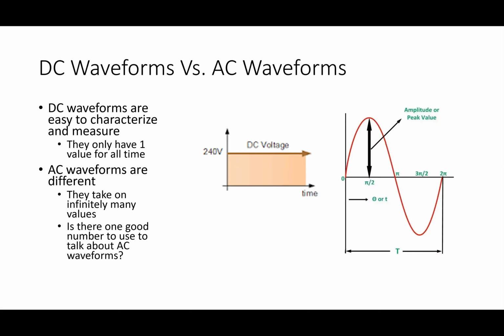And so we started out very naturally saying, well, if I'm referring to a particular voltage, you created a phasor. So if this peak value here was 10, what would you call the phasor for this particular waveform that I've drawn right here? 10 angle negative 90, because this guy's sine and not cosine. Okay, so we had those two numbers that we used to represent it in steady state, right?